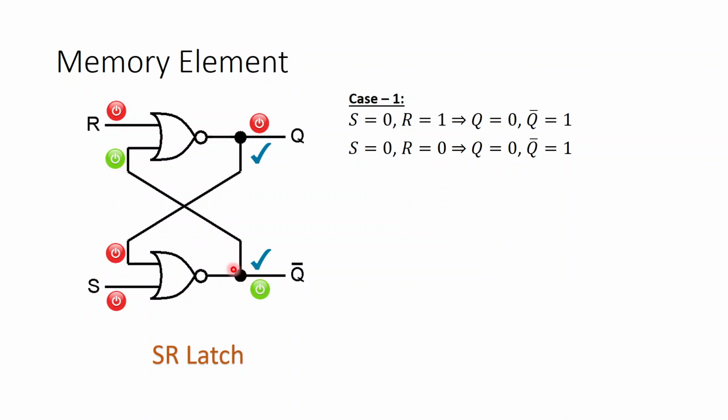So now you see this was 1 which comes at the input of the R NOR gate. So again the R NOR gate experiences a 1 at the input. That means the output remains 0. It was previously 0, it remains 0. Also at the S NOR gate, both inputs are still 0 because this has not changed. Both inputs are still 0 and the output remains 1.